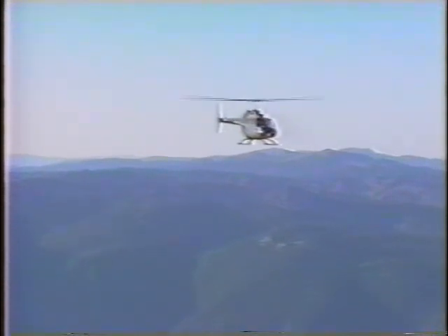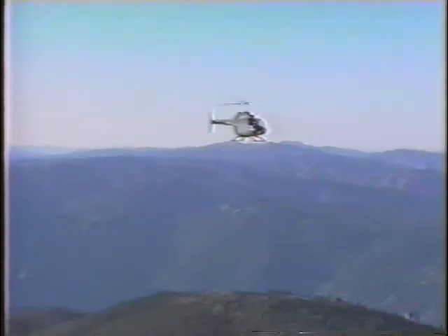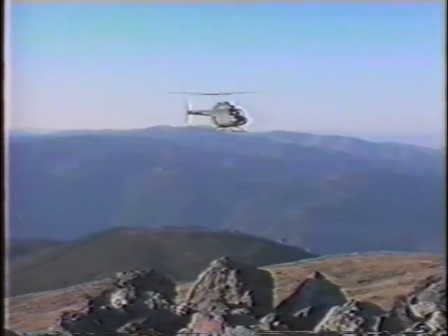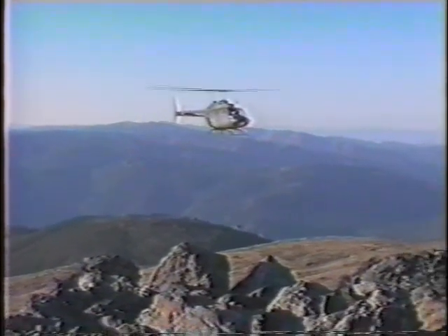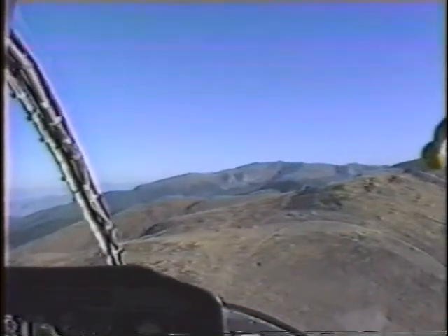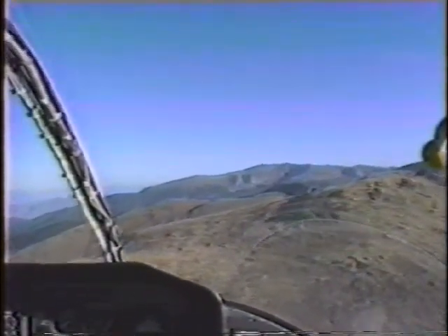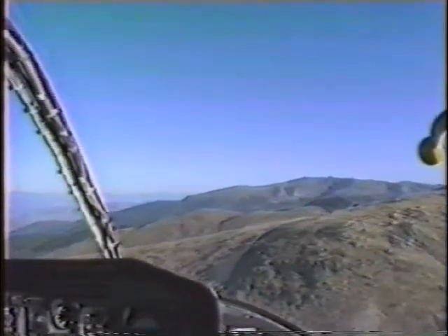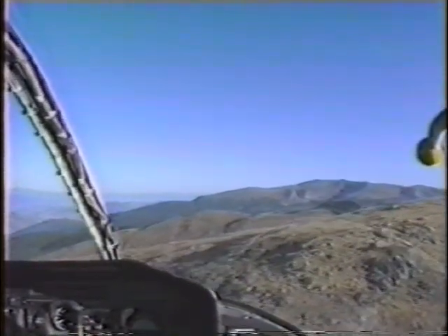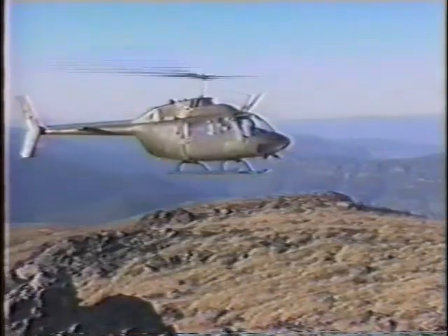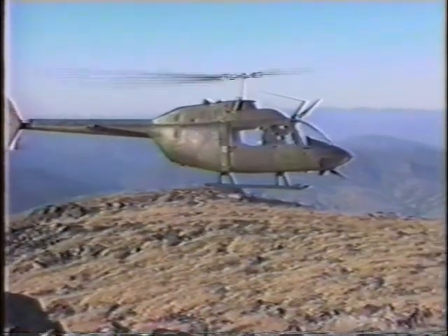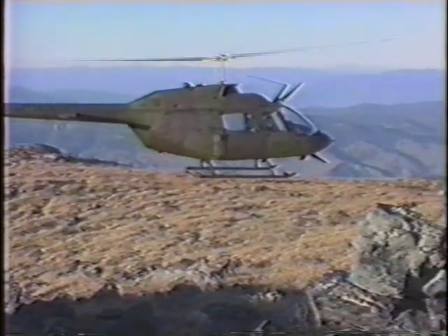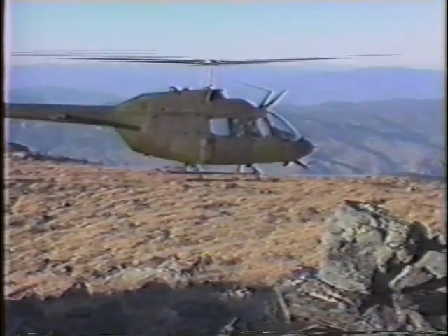On final, you follow the same procedure as your other approaches, except of course you'll have to slow to 0 ground speed by the time you reach the landing site. It takes a bit of practice to judge the proper rate of slowdown on approach at these altitudes. If you aim to have your speed down to a walking pace by the time you cross the near edge of the landing area, you should have no trouble reducing to 0 forward speed without having to flare, a move the flat approach and landing is designed to avoid.